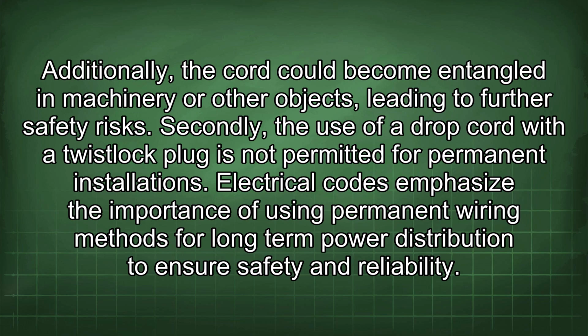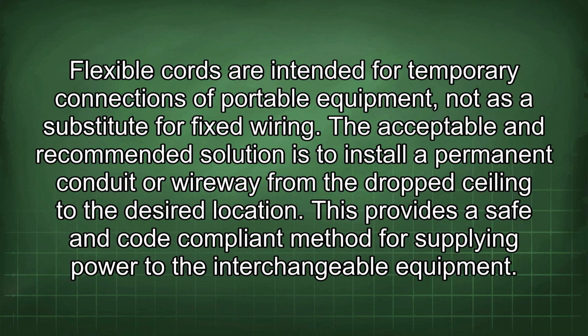Secondly, the use of a drop cord with a Twistlock plug is not permitted for permanent installations. Electrical codes emphasize the importance of using permanent wiring methods for long-term power distribution to ensure safety and reliability. Flexible cords are intended for temporary connections of portable equipment, not as a substitute for fixed wiring.